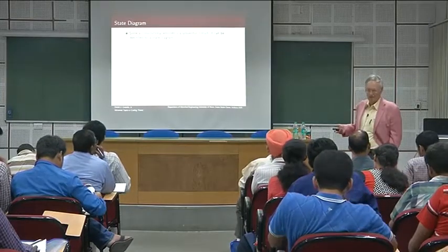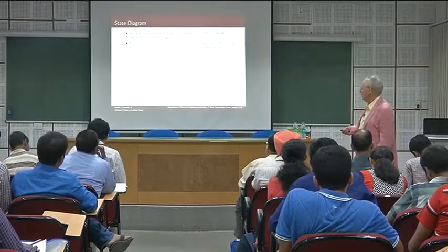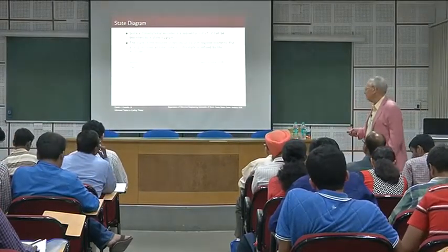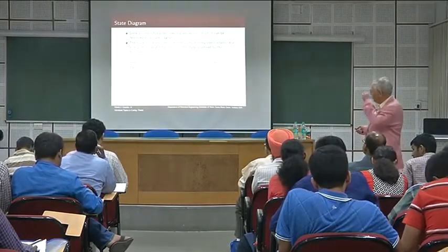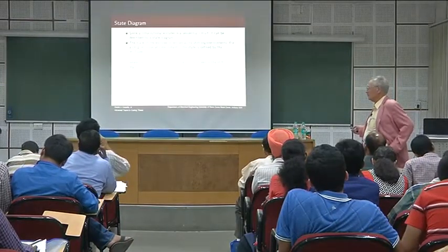Okay, now it's a sequential circuit, so it can be represented by a state diagram, just like any sequential circuit. So that turns out to be useful in terms of visualizing the properties of a convolutional encoder. So we start out by defining what we refer to as the state, and it's just the contents of the shift register.